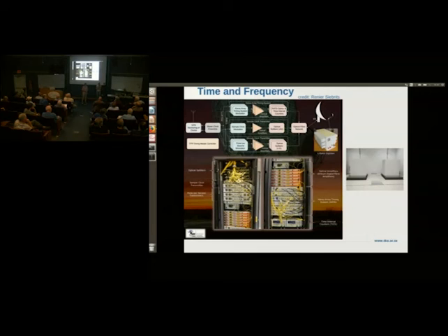As you're very well aware, in Green Bank we have a beamforming receiver that is also sending raw digitized data over fiber, and we've had some issues with that process. Is it a similar process for MeerKAT, or are you having to recover the byte lock and things like that? No, it's fundamentally a different process. We packetize the data at the digitizer.